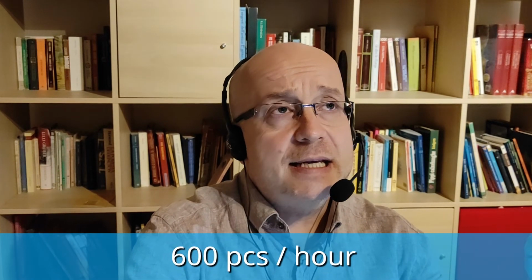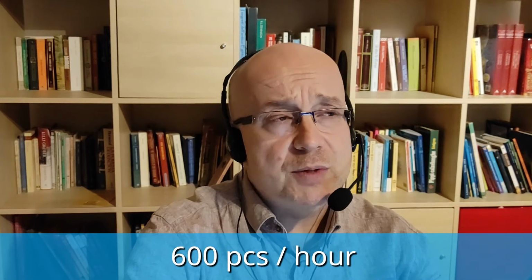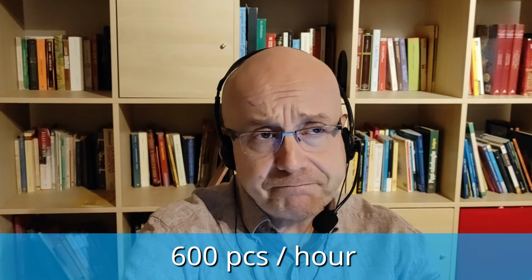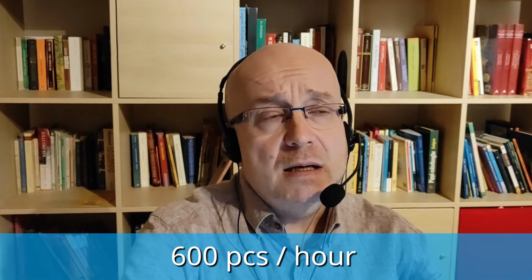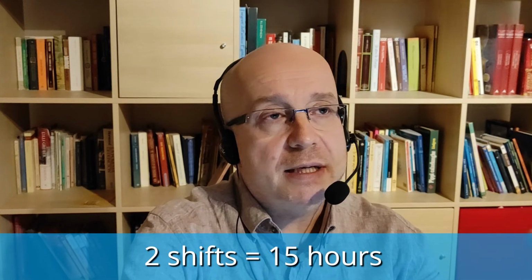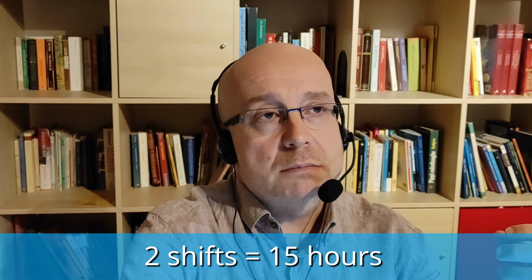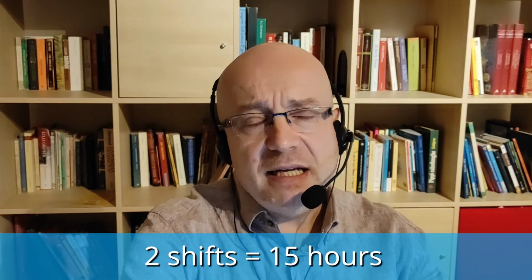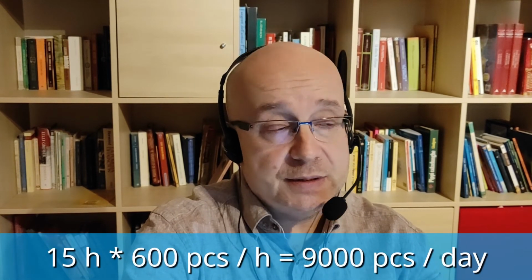Let's say 2 shifts, because at MMM's Corporation, this kind of machine would be able to produce for 2 shifts that are 16 hours. Let's consider 15 hours because maybe 1 hour can be dedicated to operator breaks or maintenance breaks. Okay, let's figure out 15 hours. 15 hours times 600 would be 9,000 units per day.